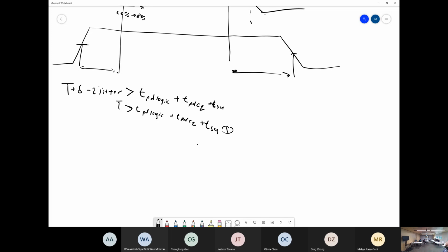Does that make sense? So let's say, calculate the speed that this can work at. Usually they might say, okay, for n logic gates, where each gate is 10 nanoseconds, you have n times 10 plus one memory element, for example. These will be fixed, so then you just solve for t in terms of n, or you have a relationship between t and n, basically. Cool. Any questions about that?